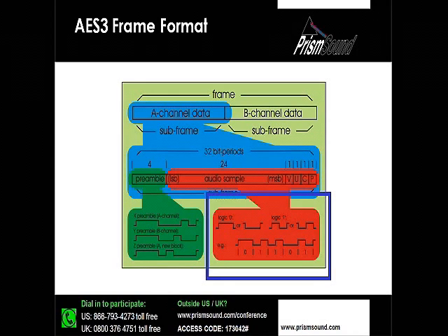They can be two different lengths. They can have different delays. There can be problems on one. At the end of the day, you have the possibility that they are not in sync with one another. So when the AES Standards Committee looked at this, they decided that the best way to handle this would be to embed the clock inside the coding of the data. And the way this is done is with a biphase mark encoding scheme.